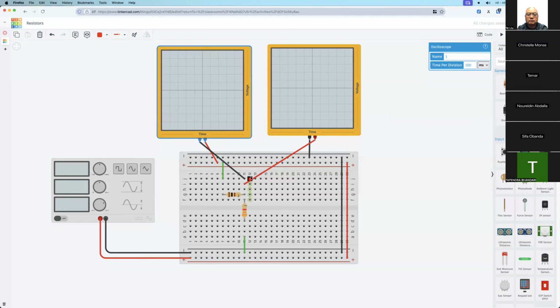So actually this means these two are connected. We can see the current flowing through this line, then here, then this one, then go to the 100 ohm resistor, then go to ground, then back to the ground of the function generator. So this means the 3.3 kilo ohm resistor is shorted. So for the real lab, we cannot do it this way, but this is the simulation.